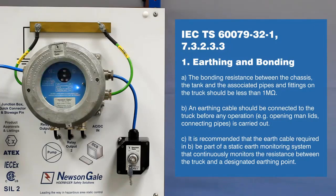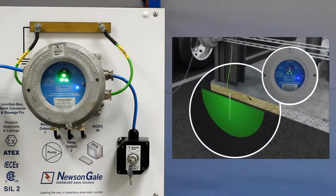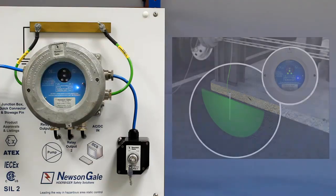Interlocking with the transfer process means product flow can be halted should the connection exceed 10 ohms. Any static generated by the loading operation is transferred from the road tanker via the Earth-Rite RTR to ground, mitigating static electricity as a potential source of ignition.